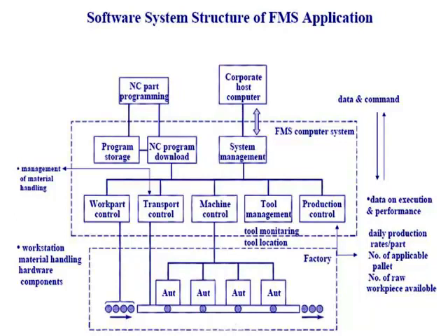So it has to send several signals for movement of parts, for starting and stopping of programs, and loading and unloading of the programs onto various machines. It also receives signals from the respective machines, such as the end of the program or breakage of the machine tool, everything. Such things will be done compositely by the so-called cell controller or system controller.